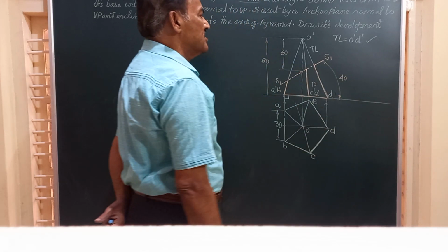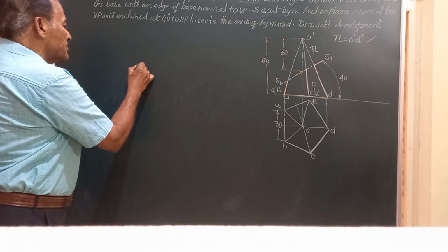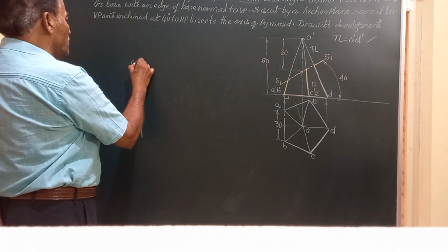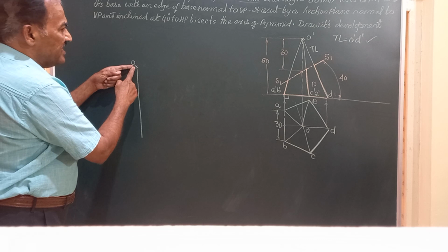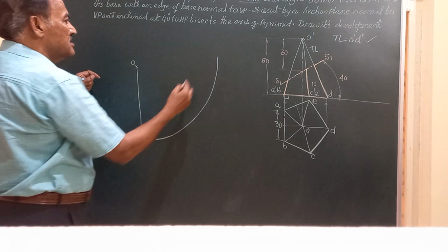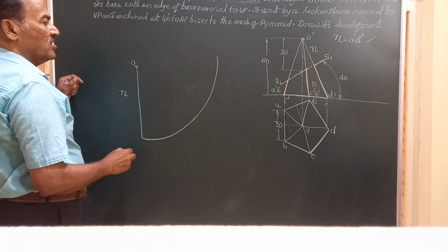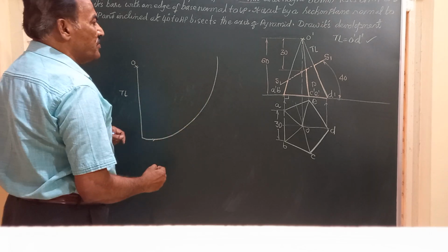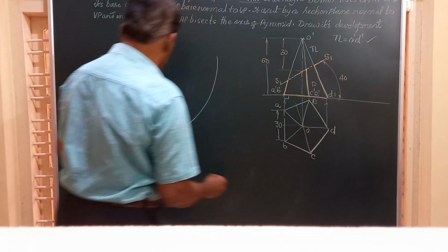Is the true length. And now friends, taking that true length as the radius, I am going to write a line here. Say this is the true length of that. O is the point, the vertex. And now friends, taking O as center, true length as radius, I am going to draw an arc. This is O. And friends, on this arc so drawn, I am going to step up 30 length divisions, 5 because there are 5 edges.